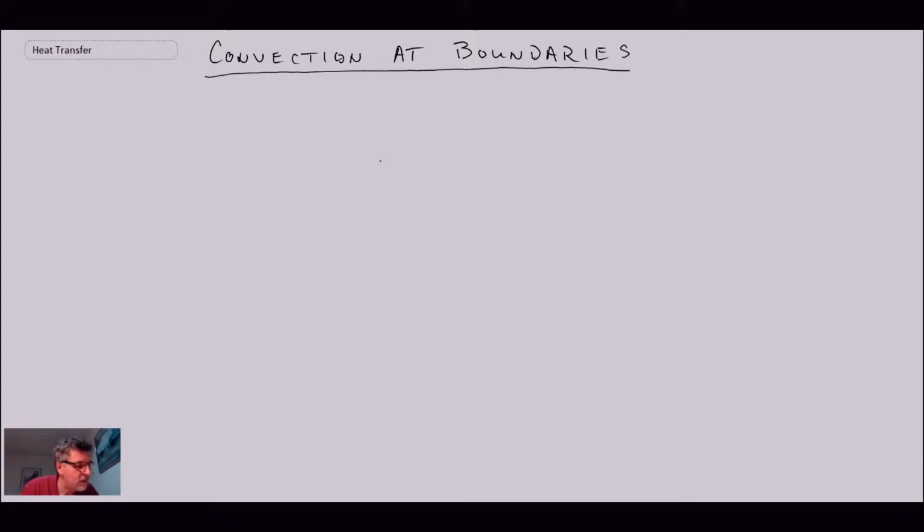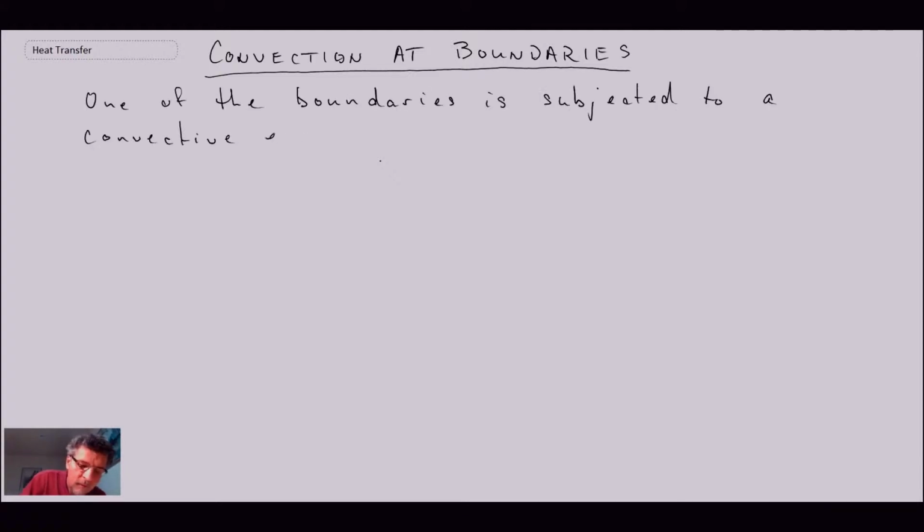And so what I'll do again is I'm going to begin by drawing out a schematic that we'll use when we come up with the equation that will enable us to determine the boundary condition in finite difference form. And so we're assuming a convective environment with convective heat transfer coefficient h and free stream temperature T infinity. So let's draw out the schematic.